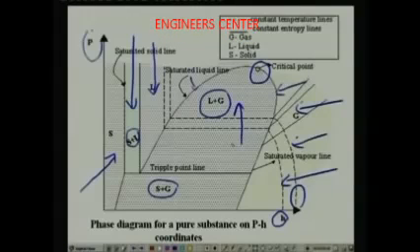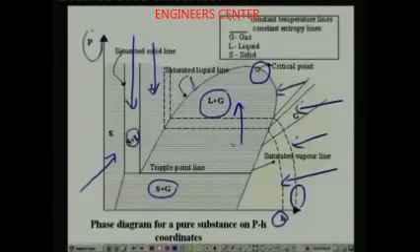And physically, when the working fluid exists below the critical point, you can distinguish liquid and gas. That means if you have collected this liquid and gas mixture in, let's say, a glass beaker, then a meniscus forms between the liquid and gas phases. Whereas if the working fluid is above the critical point, you cannot make any distinction between liquid and gas, and that region is known as a supercritical region.